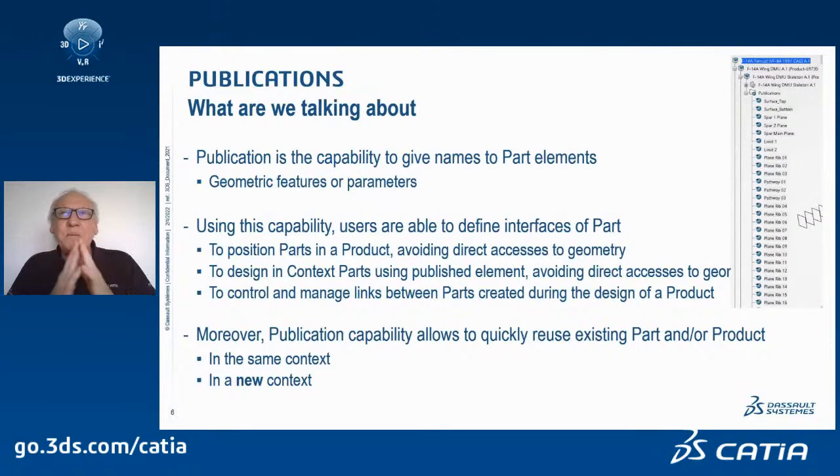One of the most complex things when you do parametric design is to achieve a very easily updatable product when there is a design change, okay? If by mistake you click on a surface in the 3D session, and the number of spans or surfaces in the surface you are clicking changes, you might create an issue.